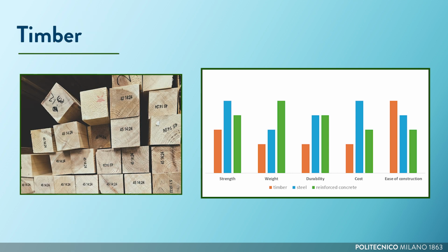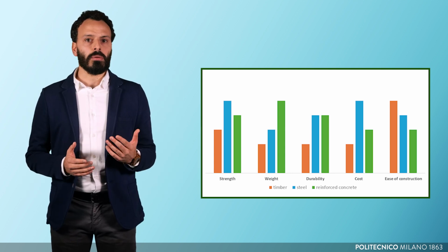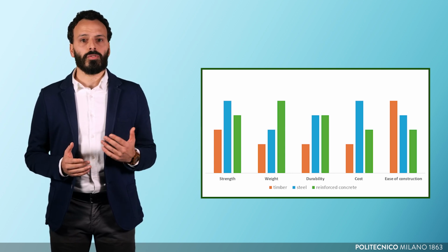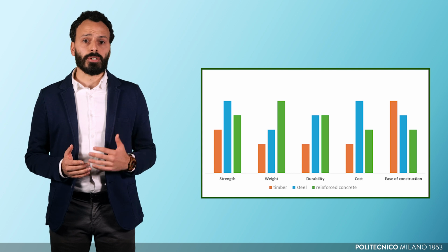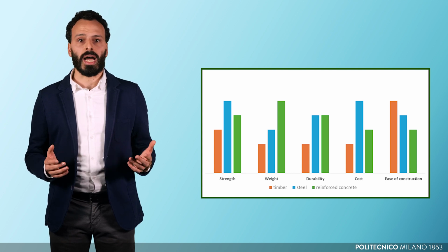In rural Africa, timber is locally available, lighter, cost-effective, and relatively easy to work with using simple tools. Timber bridges can be quickly built and require minimal heavy machinery. However, timber has limitations related to durability. In fact, it can quickly deteriorate without proper treatment. Despite these challenges, timber remains a viable material for short-span bridges, especially where budgets are tight and time is limited.